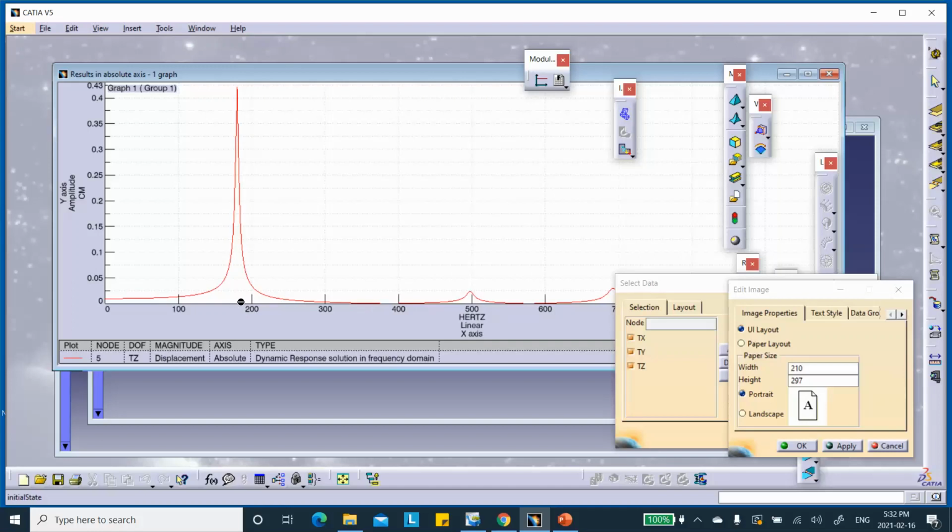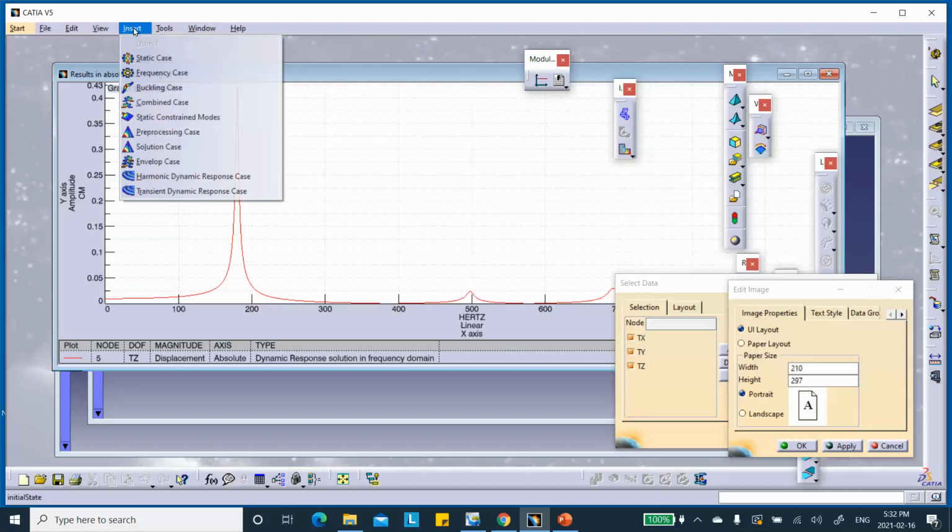If this was a fan, hypothetically, going at a certain RPM, it has an operating frequency in hertz, and then you go here and find out the amplitude of the displacement at that center point under this fan, and there we are. So this is the concept of frequency response, or harmonic dynamic response, etc.